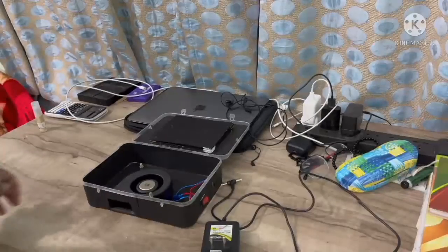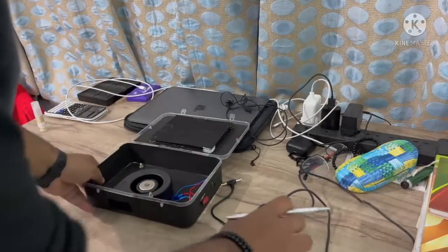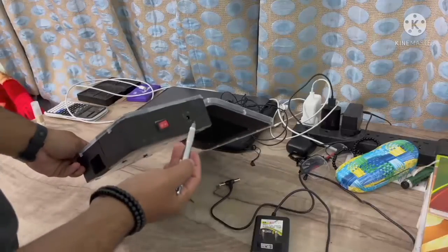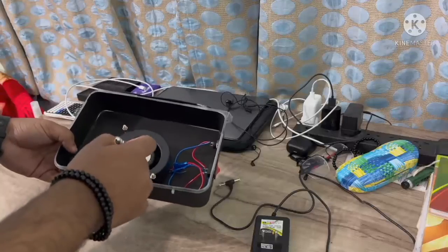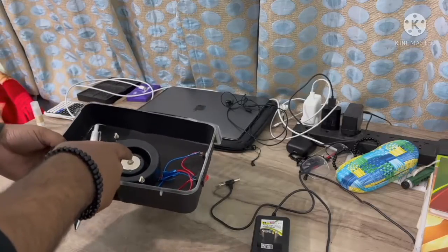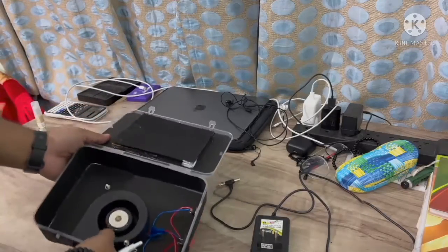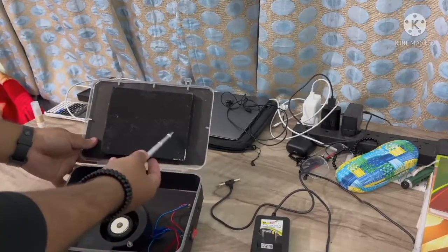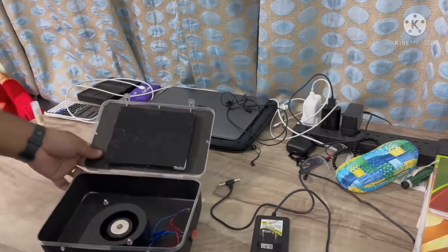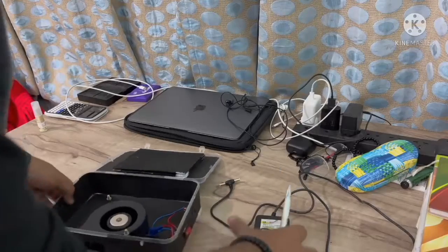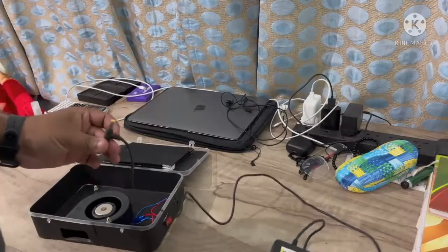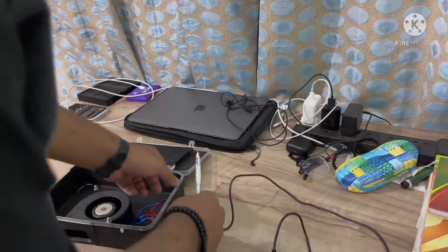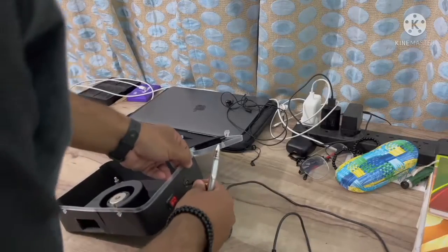Okay, so I would be explaining the air purifier, and let me run you through the components of it. This is a DC socket, this is an SPST switch, and this is a 12 volt air blower, GPZ A12 type, and this was a carbon filter sheet, and I have made it into 4 layers. For the power supply, I'm using an AC/DC converter, 12 volt 1 ampere adapter, and I would be connecting this to the DC socket.